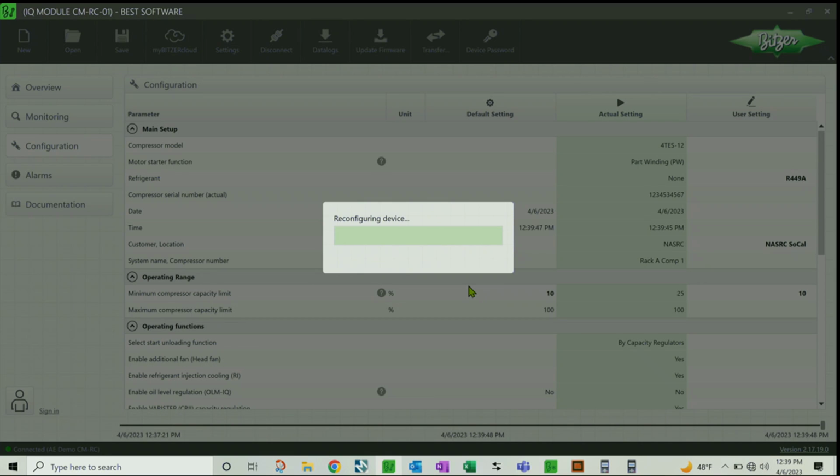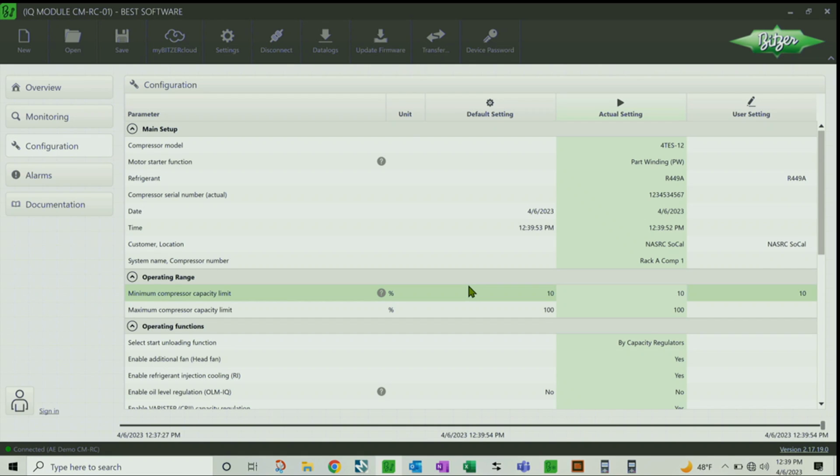While it does that, all right. You have to run its own independent power? Yeah, so it does need a minimum of 3 wires connected to it. Power and 0 to 10 if you're using control of the CMRC. If you're doing Modbus, then there's a whole another set of Modbus wires. But so the 24 volts, or what's the power supply? 120 or 230. Oh, nice. Internally, it has 24 volts and controls a lot of the functionality with 24 volts, but we bring in 120 or 230.